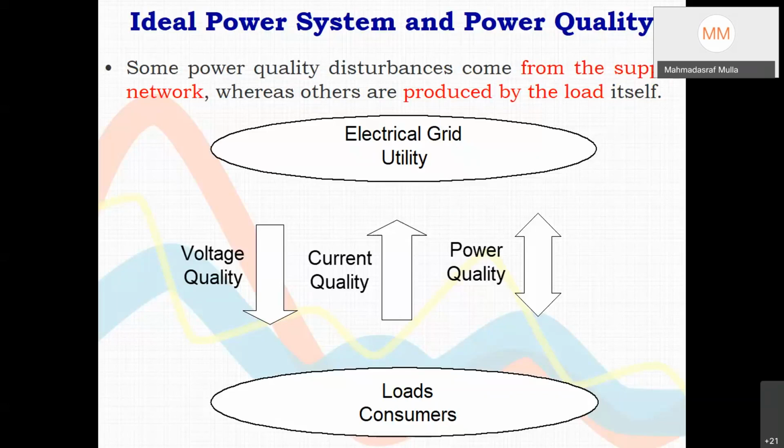So the power quality problem in this new distributed generation environment is quite complex, and older theory will not work out. For example, in protection systems we assume that the generator voltage is fixed. Now with a solar inverter, if we short circuit it, nothing will happen; the generation itself will stop, and nothing will happen to the generator.